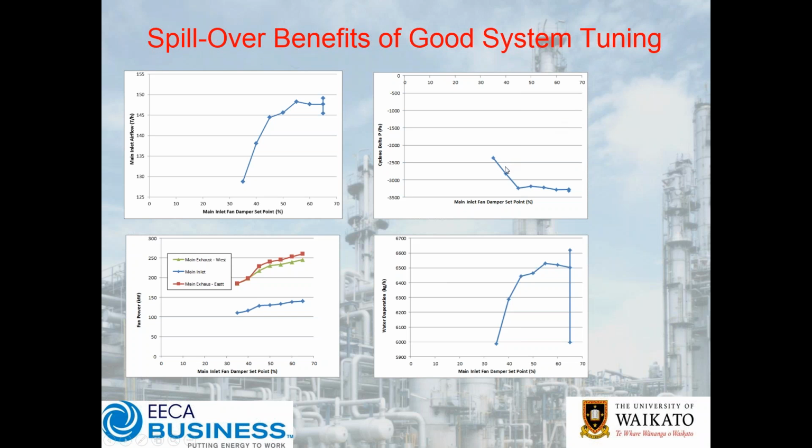Now, here's a really good example. I can't go into too many details, but here's a system where we had a range of airflows, and you can see there's quite a performance there, and then there's a bit of a peak in here. Then what you'll see is there's a pressure drop as a part of your system in terms of a cyclone, which was a key separation vessel in this process. You can see your fan powers both on the inlet and the exhaust. You can see that we had an imbalance, and as we come down and we get the system into control, everything's looking really nice. Now what's interesting is this bottom curve here is actually an evaporation rate. So if you think about this big arch here, this is effectively capacity of the plant.